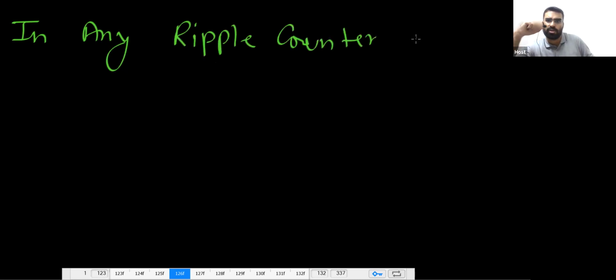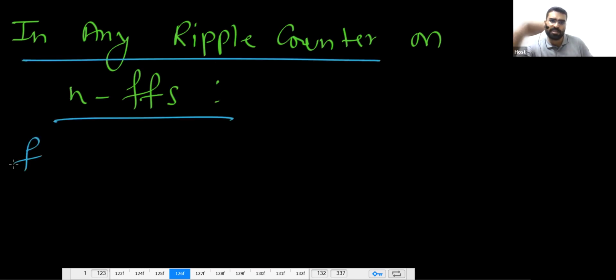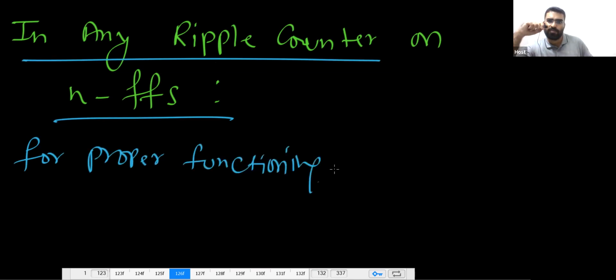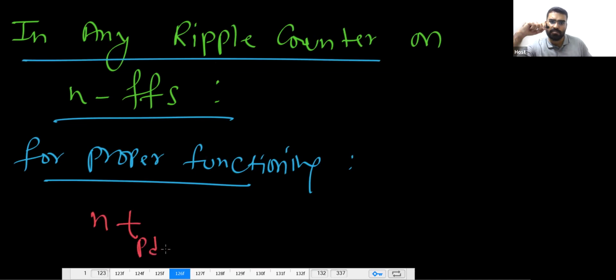In any ripple counter with n flip-flops, what should happen for proper functioning? This should happen: n times TPD must be less than or equal to your clock period.